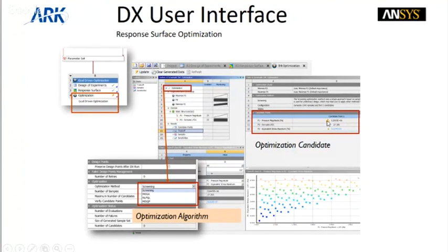This is what is called goal-driven optimization, wherein we set the value of the desired output which we require. For example, if you are taking factor of safety into consideration, I have set the factor of safety as 2. Based on that, the solver will tell me that by changing the pressure magnitude to so-and-so value, I will get the desired factor of safety. Got it?